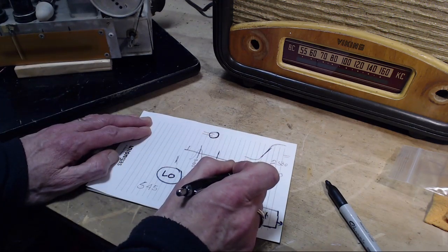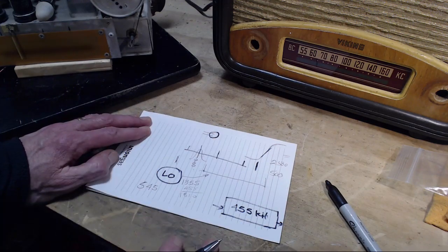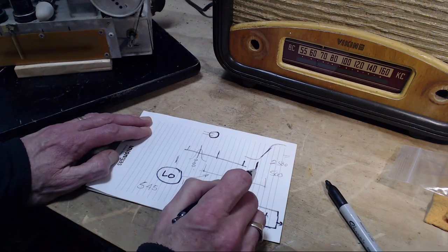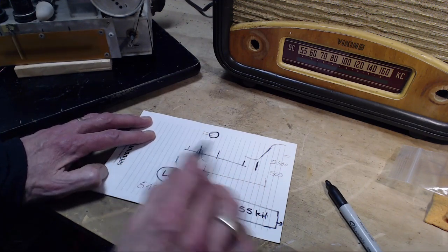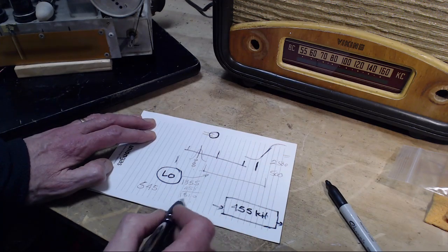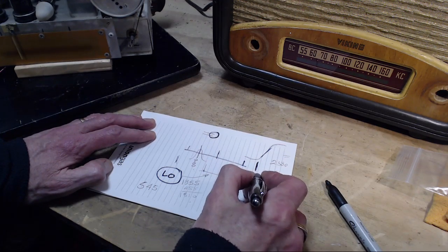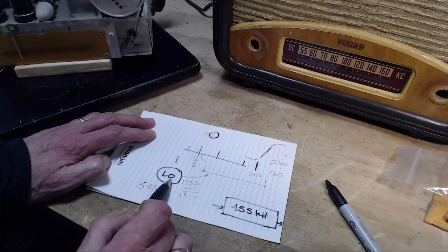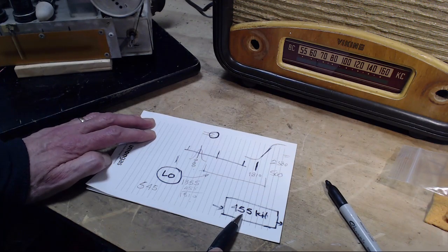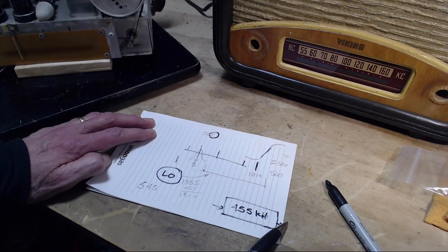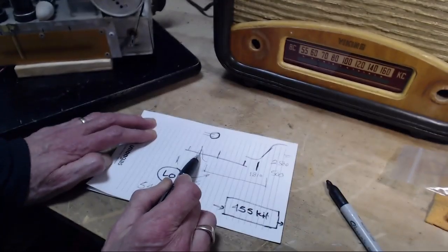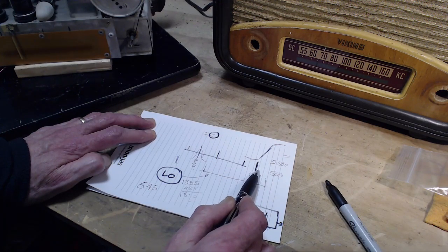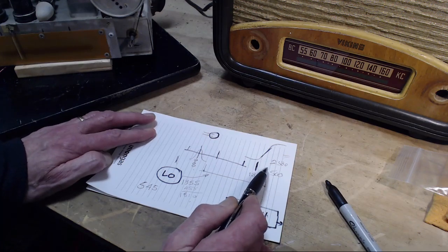If there's nothing there, if there's no signal there, there's no problem with this. If there is a powerful signal there, another radio station, a noise signal, who knows what, some guy on his ham radio, who knows what it might be, at that location, which is 1810, it has the potential to mix in the mixer tube with the local oscillator and produce another 455 signal, come through the IF and out to the speaker, and we could hear it. You'd be looking at the dial pointer swinging back and forth here while you're tuning, but you're actually listening to this. So what stops this?